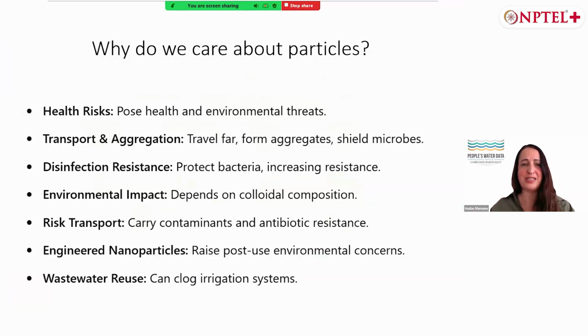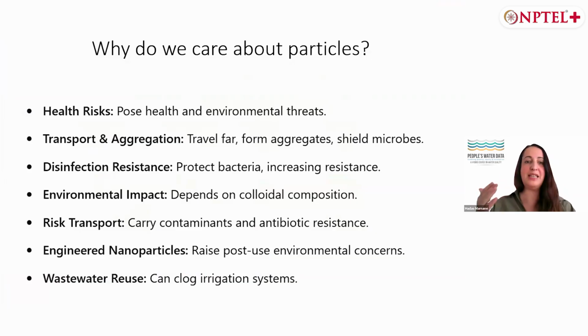So why do we care about all this? Why do we care about the turbidity value of water? And again, please remember that the turbidity is actually an indication of the particles in water, but it mostly provides an indication of light scattering by particles. And if we take the water sample and measure the particles using the different particle size distribution analyzers, we will obtain different values. But turbidity gives us a very good indication of the particle content of the water, but it's not perfect.